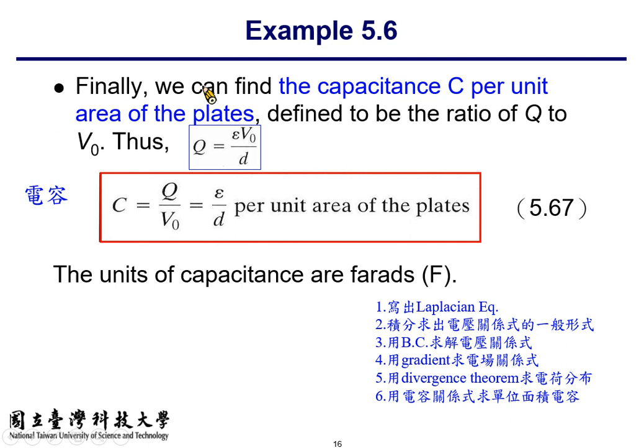But to cope with the capacitor manufacturers' needs, for man-made material, you can create ceramics with relative permittivity up to 100, 1,000, and even 10,000. That's what I heard of. So that's a relatively large number, and as a consequence you can create a large capacitance.